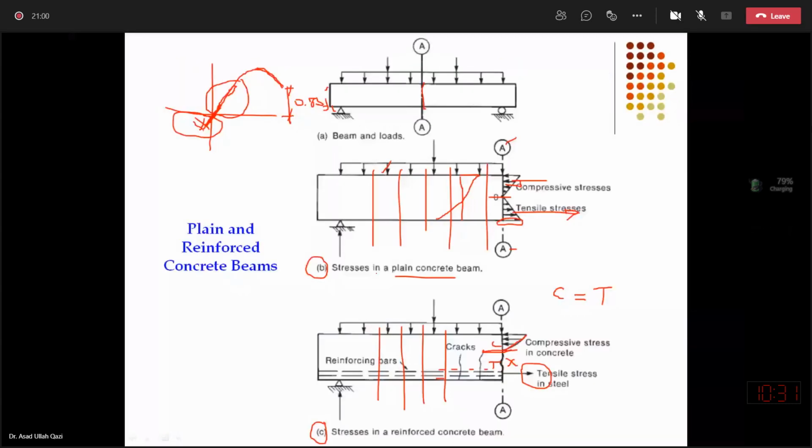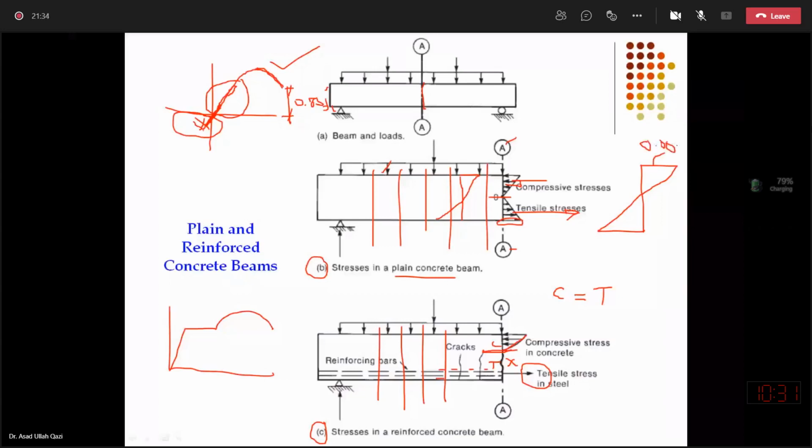As I mentioned earlier, if this is the stress strain relationship of concrete and we know the stress strain relationship of steel, so when I have a strain diagram and I'm recording the strains in the cross section, so if I know that the concrete in the topmost fiber has a strain 0.001, because I am measuring the compression strain by putting the strain gauge on the top of the beam at the midspan section, and during load increment I measured that this is the strain value at top corresponding to some load, I will go to stress strain diagram, and if this is the 0.001 strain corresponding to this,